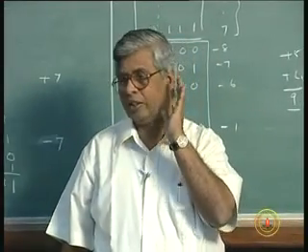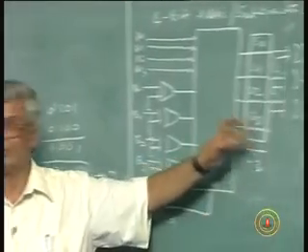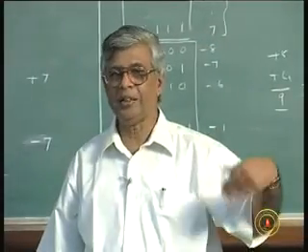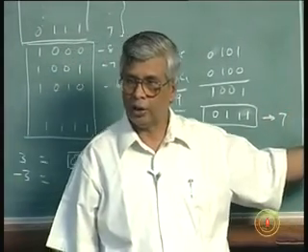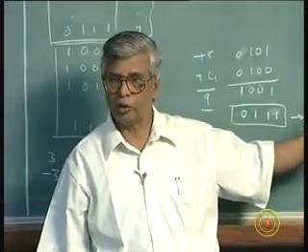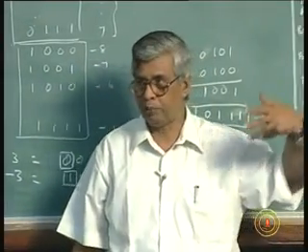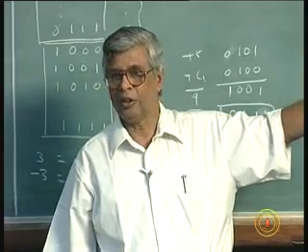And further, if the result is negative, you can leave it as it is. The best way is to leave it as it is and say it's a negative number because the sign bit is 1. People understand it's a negative number, so the value is not that. If you want to know the actual value, you will have to take the 2's complement. But if for some reason you have a compulsion to display it as a sign magnitude number, you have to do one more 2's complement, which will involve extra hardware.